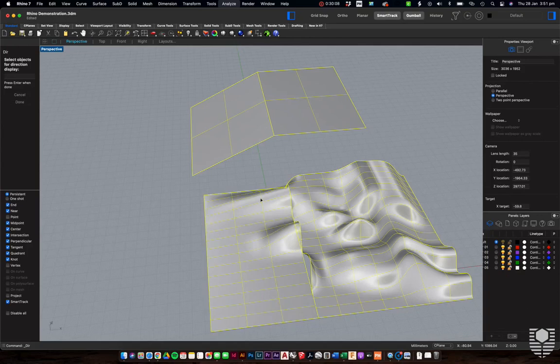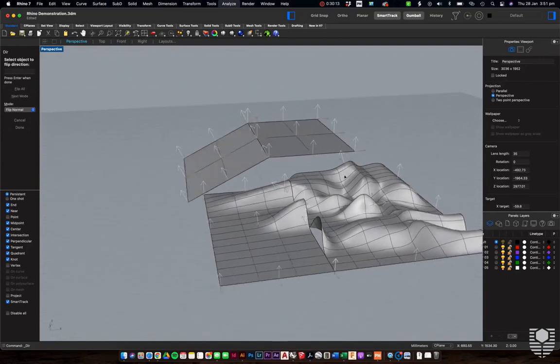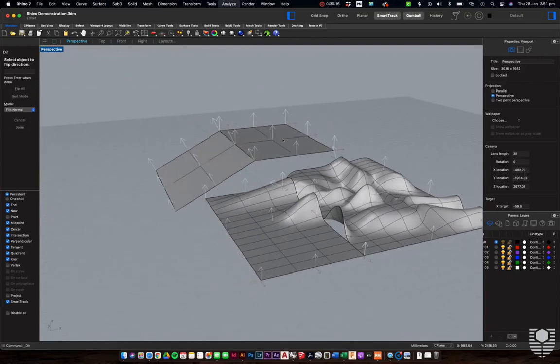Selecting our objects, we're going to select all of these surfaces that we have here, and we can see that we've got some white arrows, some red arrows, and some green arrows. The most important ones when we get into our 3D printing later are the white ones. These are the surface normals, and what that means is that at any given point, wherever these points are taken, the perpendicular direction to that exact spot. So for this surface, perpendicular from this straight line here would be upwards in the z-axis. Or if we're further along the curve, we can see that perpendicular is going in some different directions over here and around over here. It's always perpendicular to wherever that spot is, and that's our normal.